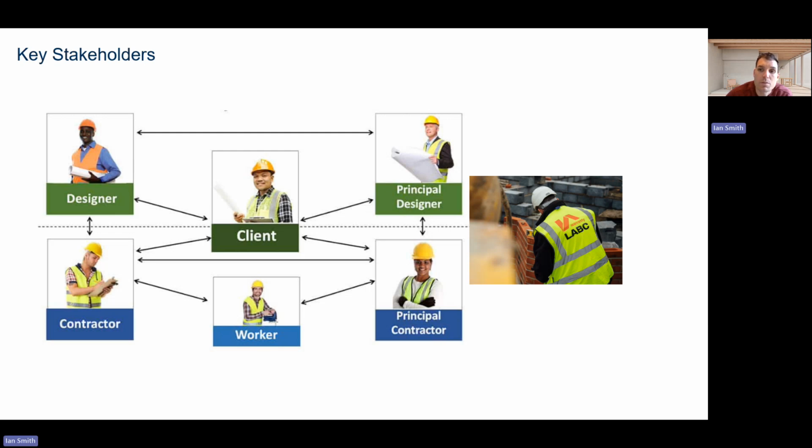Planning also allows potential risks to be identified and mitigated. For example, if we complete site investigations, it may reveal poor ground conditions or underground services, as we've highlighted, which could influence our excavation methods and foundation design. So by identifying these issues during the planning phase, the project team can develop solutions before construction begins, such as, as this underground service doesn't fall within our excavation area, it won't cause us a delay.